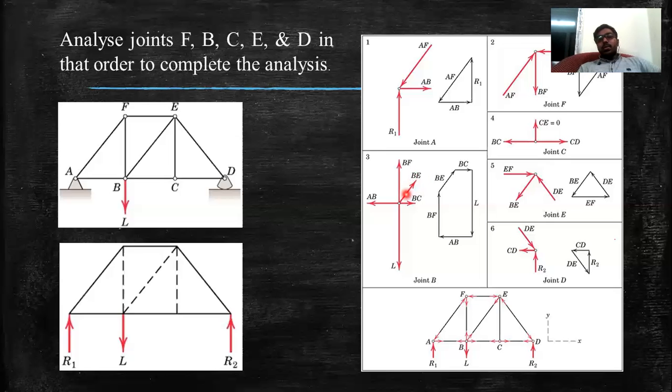And suppose we consider a force to be compressive, but after calculation this force comes out to be minus 5 kilonewton or minus 10 kilonewton, then ultimately in our real life structure, this particular member is undergoing tension. That is one important thing you have to understand. After solving for all the member forces, if taking tensile value the result is positive, then the member is undergoing tensile forces. And if taking compressive forces the member is undergoing compression, then it is compressive forces. And if the value is negative, then it will be the opposite forces.